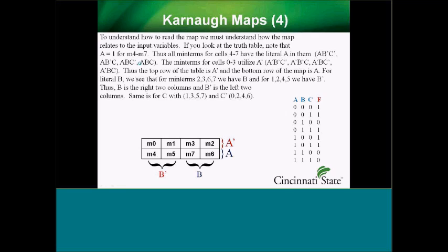Finally, I say if you look at C, and I want them to think there's nothing special. This could be X, Y, Z, or PDQ, or whatever. But C is your least significant bit. One thing you want to realize is that C basically splits into even and odd numbers. So it's 1 for all the odd numbers, and 0 for all the even numbers. So you can pick those out. Such as this is C, and those 4 are C prime. Keeping in mind that those 2 are connected, and 0, 4, 2, and 6 are all connected. So this is basically how the map is organized.